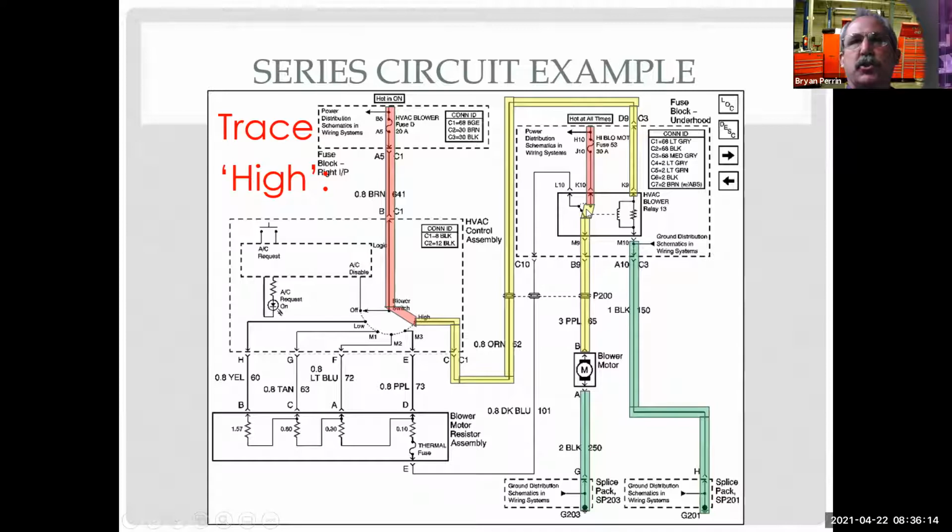And because it's cheaper for me to manufacture the car and put this relay in than it is to build a heavier switch here, because I don't need that heavy switch for these 4 other settings. So I'd be spending more money where I don't need to. So manufacturers make those decisions. This by no means is everybody having a separate circuit for high. Some of them run them all through the switch.